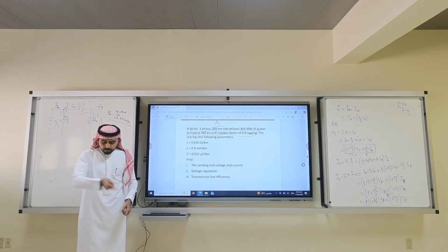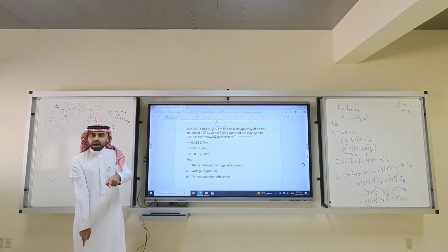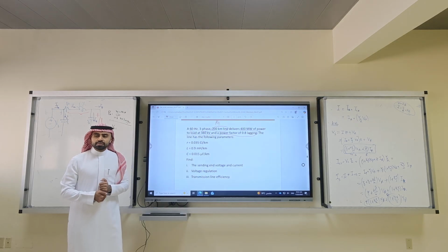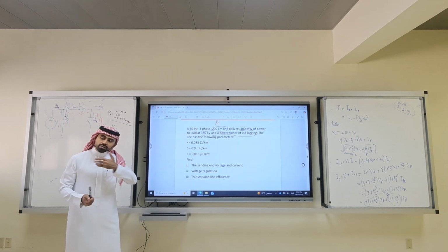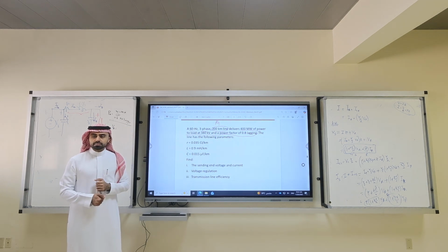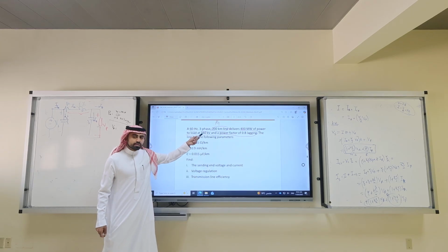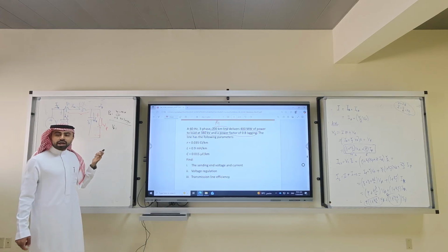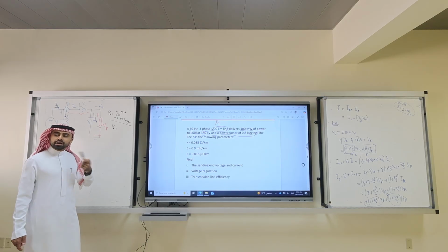But if he puts the equipment on one line and on the ground, he closes the circuit. The language of communication is line to line. So what should you solve for? Single phase. Now, if he tells you delta connected, you know line to line is equal to phase.